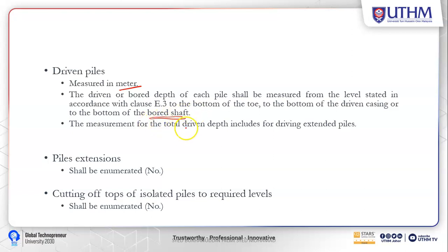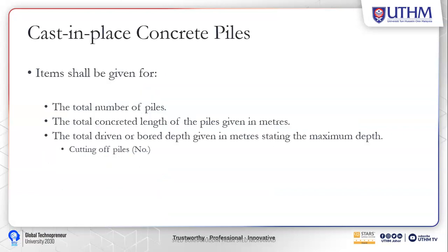And then the measurement of the total driven depth includes driving extension piles. Pile extension sometimes shall be enumerated in number, and then cutting off of the top of isolated pile also in numbers. This is how we can determine the unit for each item for piling work. Okay, next we look into the